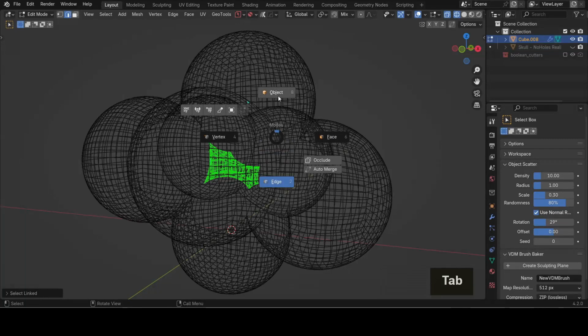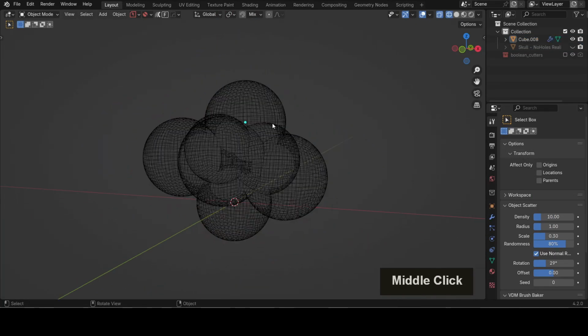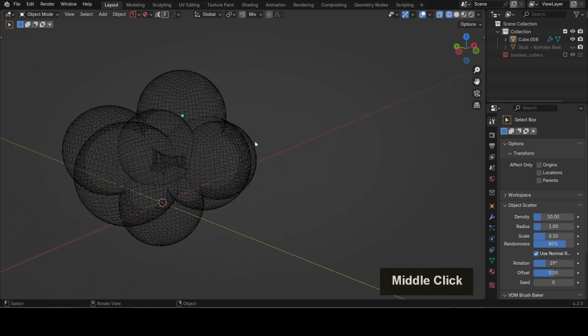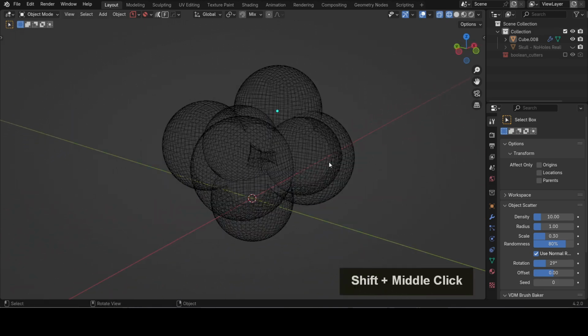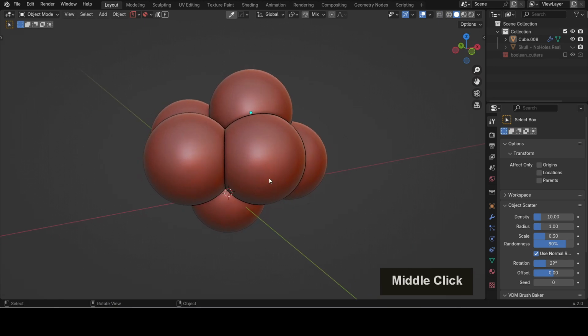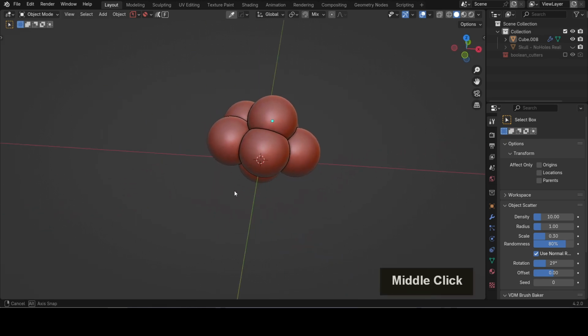Now, in David's instance, he was asking about this for files taken from STLs and other places, and this can also be created when programs like 3D Builder attempt to fix issues in geometry where there's sort of internal faces crisscrossing over each other, which is why I'd always recommend using booleans to combine everything together and then check it in 3D Builder, not the other way round.